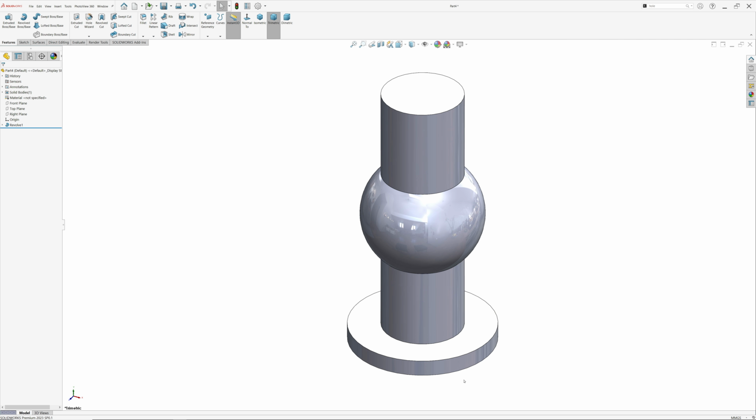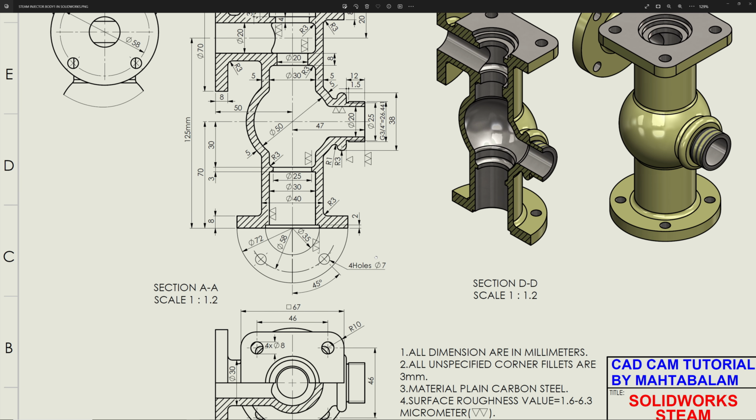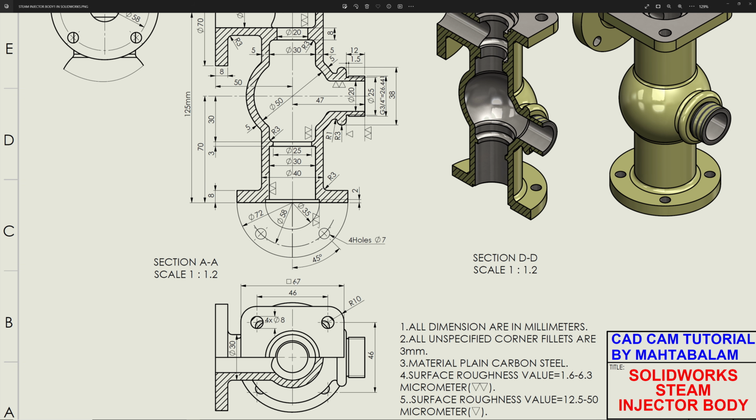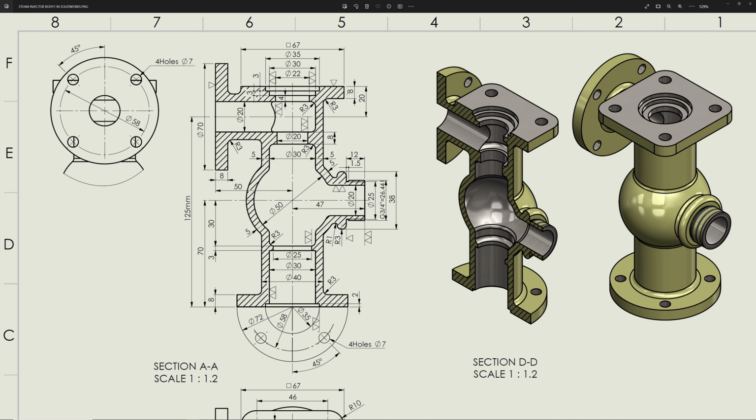Okay. Now at top there is a flange, a square flange. See 64 square. Then there are holes, 4 number of holes, 8 diameter, and 46, 46. Then there is a corner fillet R10, and thickness is 8 millimeter.